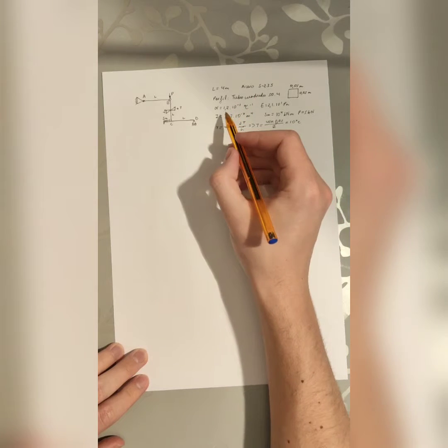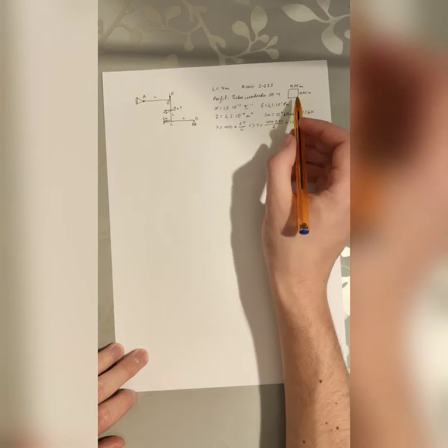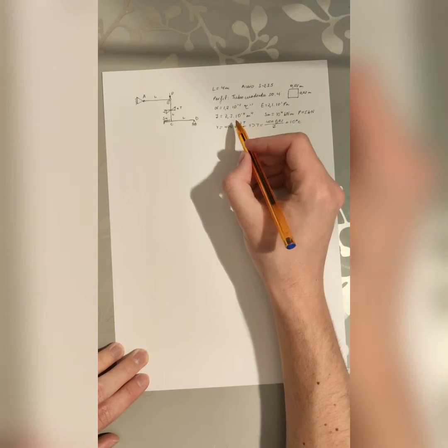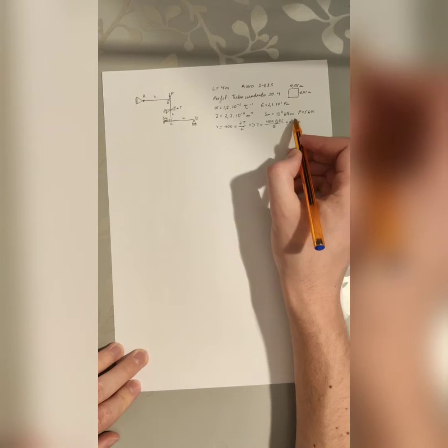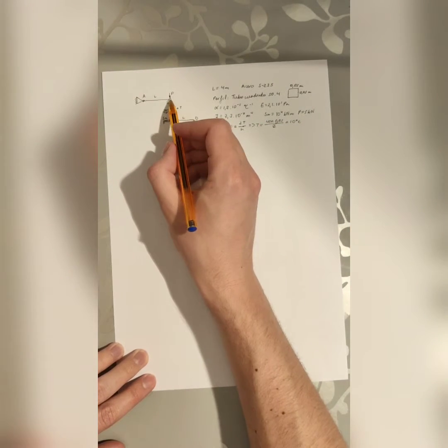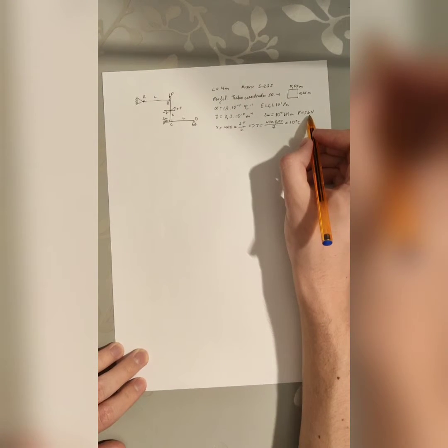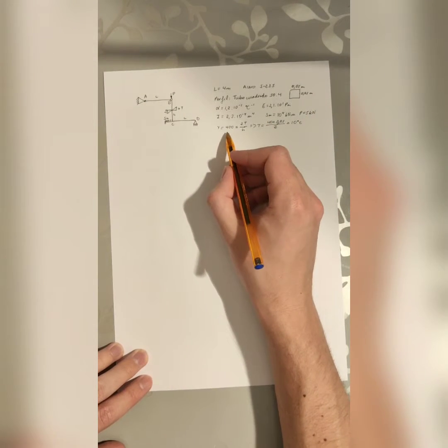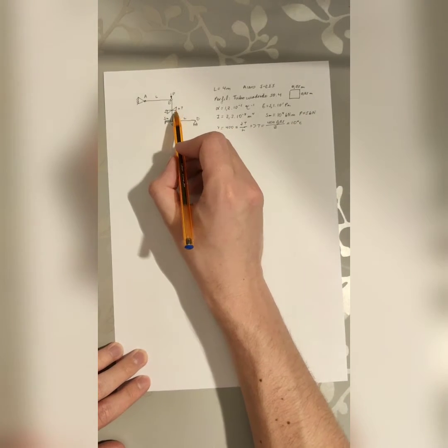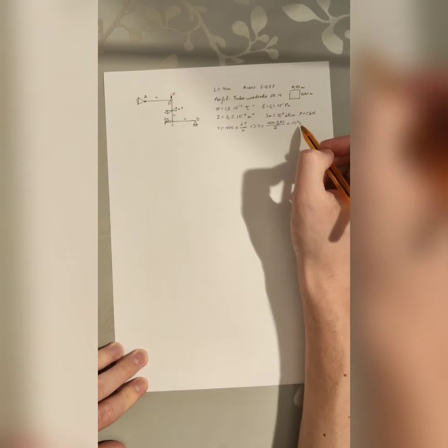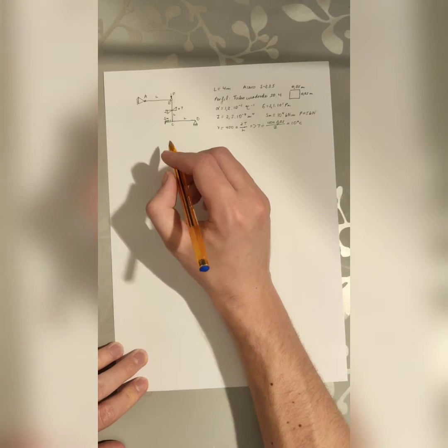and this steel has this temperature expansion coefficient, this elastic modulus, the profile has this inertia, and then the spring has this rigidity, and we have a force at B, force P of 5 kilonewtons. The temperature gradient is 400. Therefore, the maximum temperature on this side, the positive side, is 10 degrees, and on this side it would be 20 degrees less, minus 10 degrees.